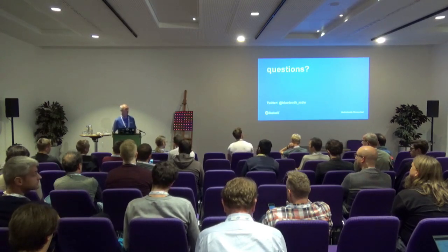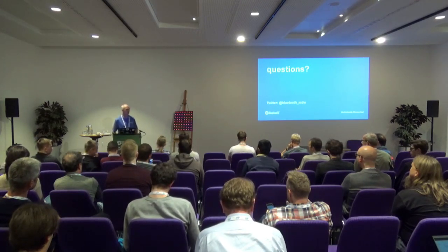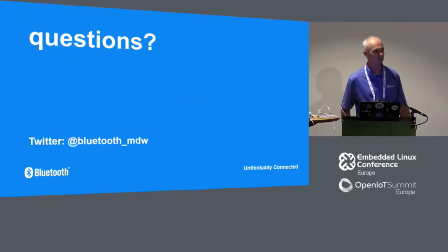So we at the Bluetooth SIG have done no comparisons with respect to power consumption, because that would be more of an implementation thing, and you'd probably be better off talking to people like Nordic about that. We have, of course, done some thinking about differences at the level of the specification. I know very little about Zigbee, I'll say that right now, but the one I'd point to straight away is the reliance on 802.15.4. It makes the radio quite slow, 250 kbits per second. Bluetooth mesh relies on Bluetooth Low Energy 4.0 or later, so that's 1 megabit per second. Bluetooth 5, you may know, can go at 2 megabits per second, but we don't require a Bluetooth 5 stack.